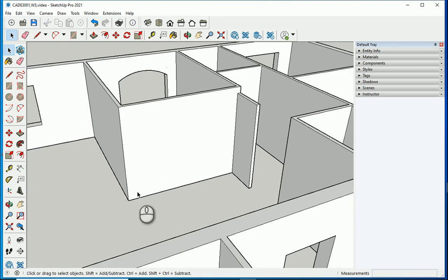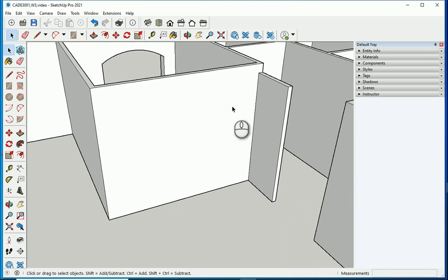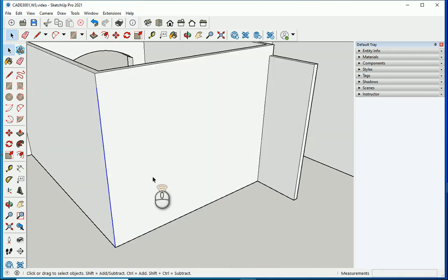And now the stairs are gonna go from here to here, and they will go to the rooms. So how does the stairs work? We're gonna need to know the height, so I want to go with L. I want to draw one line from here till above here. If you hover the mouse around here, then hold shift, it knows that you want to get that dimension. So I want to click once here. Also, I want to click once here.